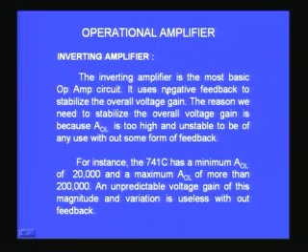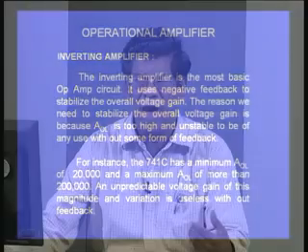In many of the books you would find inverting amplifier will be given as the first circuit, most basic circuit in op amps, because you also have here negative feedback, and the negative feedback stabilizes the performance of the amplifier, you know that. When you have negative feedback, the amplifier performs much more reliably, because the open loop gain can be different, starting from some 20,000 to some 200,000 you can have variation depending upon several other parameters of the amplifier. So then it becomes unpredictable what will be the output voltage, but by giving negative feedback you try to stabilize the amplifier, and therefore the amplifier becomes much more reliable. That is the advantage of introducing negative feedback.